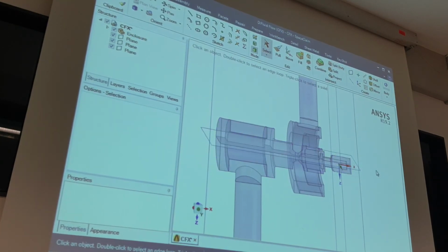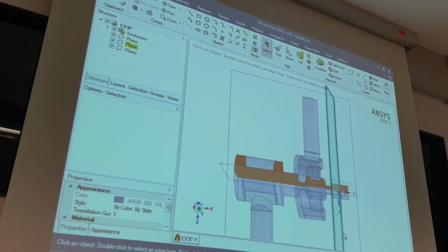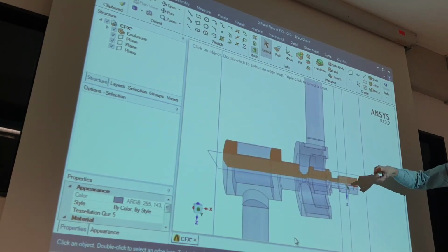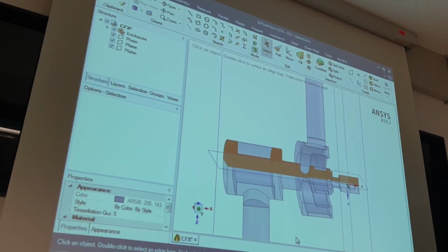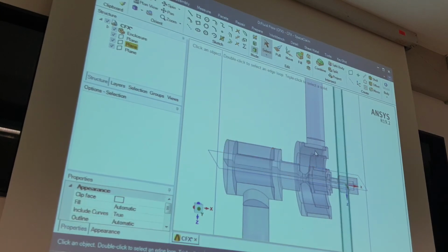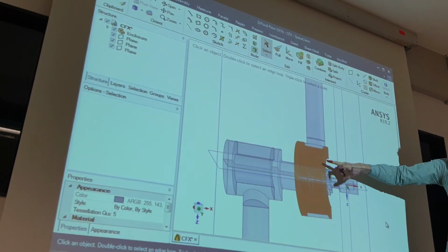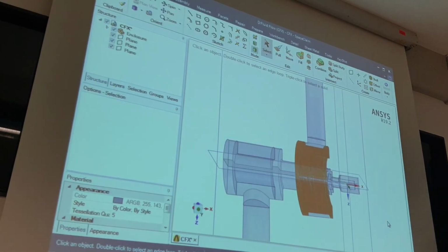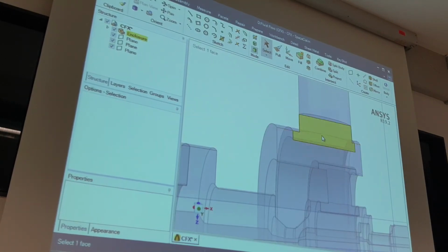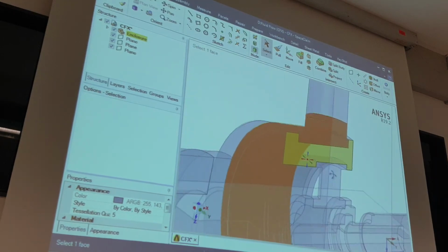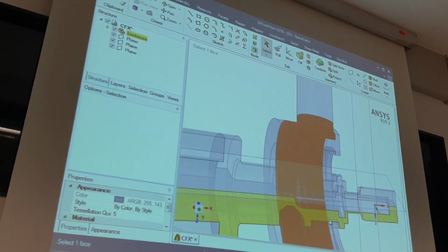So if I do it like this now, then look, here it is completely sweepable. In this direction I have the same geometry in the same direction. So this part I can also make hexamesh: inlet, outlet, same direction. So in reality, I divided only the connection parts between them. And then I can create hexamesh.